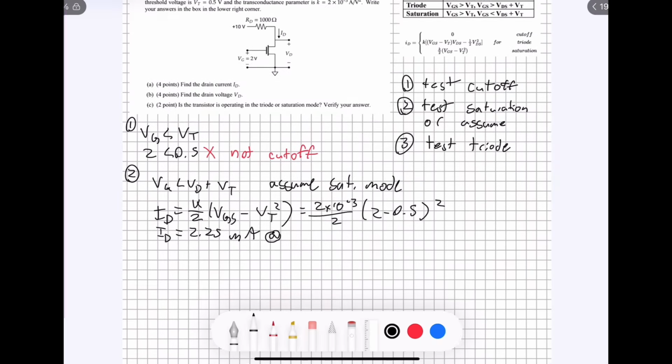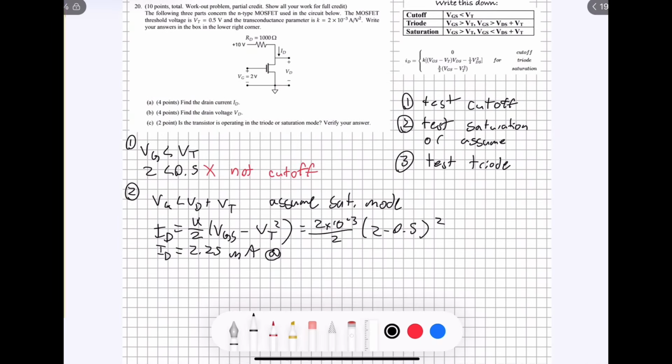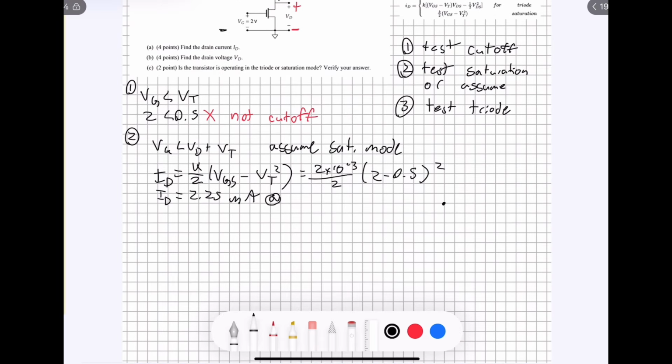So we can see that if we want to determine VD right here in the circuit, one way that we can do it is by finding the voltage drop across here and then subtracting the voltage drop across here, because that's going to give us our voltage drop of VD. And I can kind of redraw that to make it a little bit more clear. There's a resistor there.